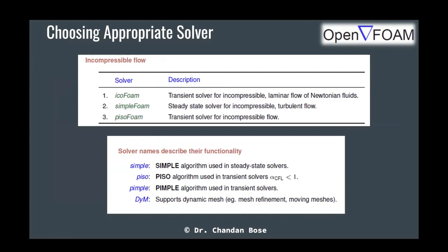And you have to actually understand the CFD solution mechanism, that is, what these solvers do. You can go to the source code of these solvers and match it with your theoretical knowledge of CFD or the mathematical foundation of the solution mechanism, such as what the stability criteria of that particular scheme are, right?